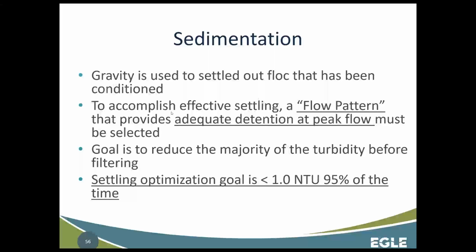It's impractical maybe to build your basin just as an open basin because it would have to be unrealistically long in order for there to be enough detention time for the particles to settle out. So instead, we'll put in some baffles and make that water take a serpentine flow through the settling basin. Maybe similar to that flock basin that we saw, make it go up and down. It basically makes the residence time for those particles increase without increasing the dimensions of the basin.